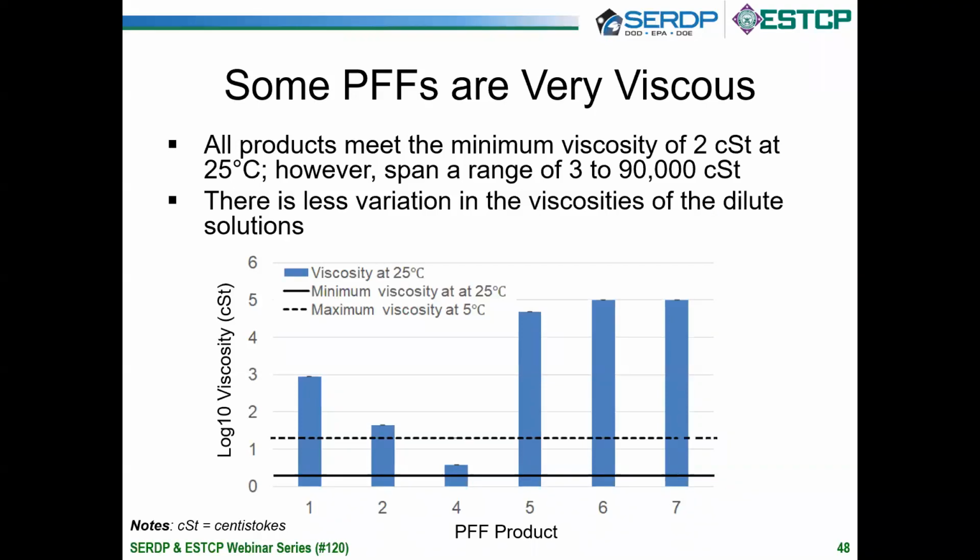There is a trend that we see in that these PFF products are getting very viscous. And the reason for this is that we're trying to replace AFFF, whose primary mechanism is film forming over the fire and sealing the fire that way, as opposed to a high viscosity that gives you a more stable foam.